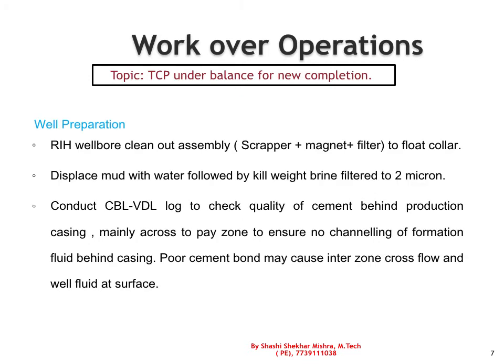Before perforation we have to prepare the well. In a new drilled well, usually the well is filled with mud, and this mud is normally not suitable for perforation because of the lot of fines in the mud that will damage the formation or may clog the tunnels after perforation.